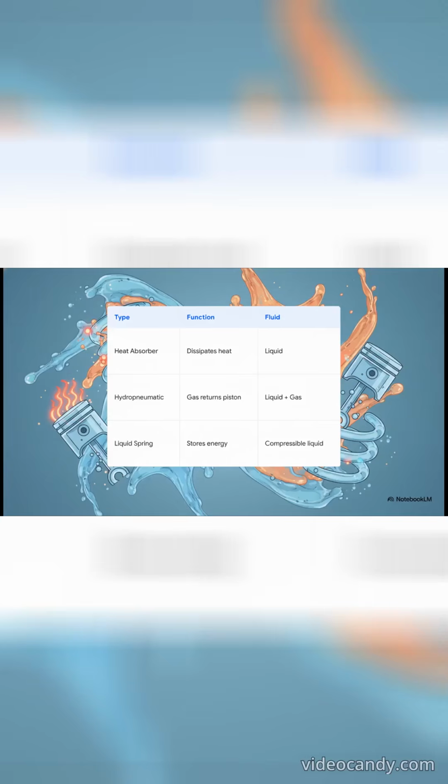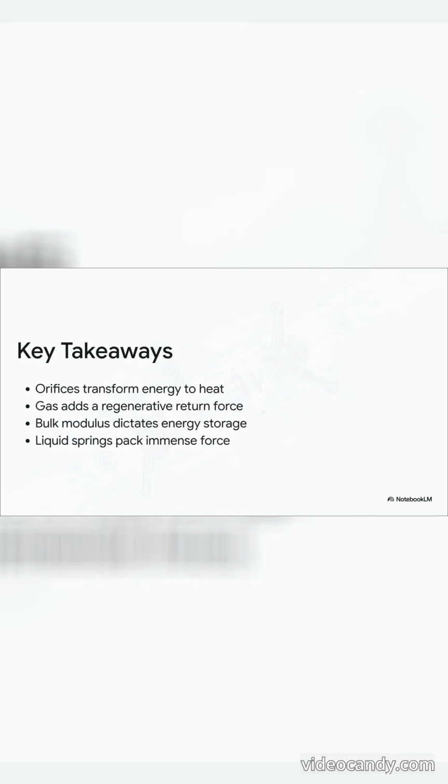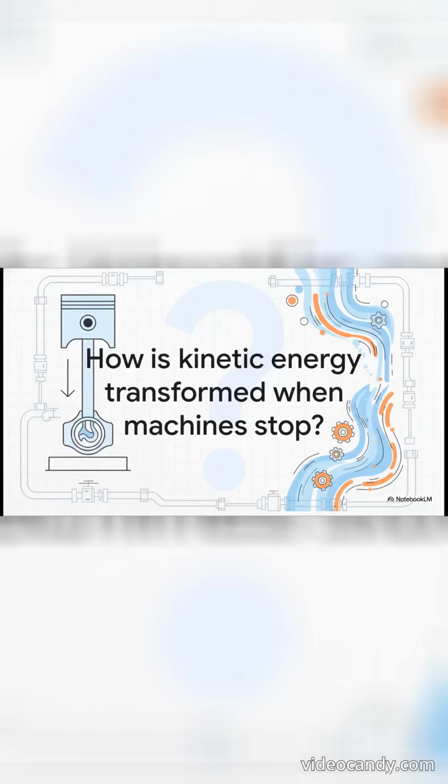All right, let's step back and summarize everything we just covered about fluid power and rapid deceleration. Heat absorbers just dissipate energy, whereas hydropneumatic and liquid springs actively use compressed fluids for return forces. Remember, orifices turn energy to heat, gas adds return force, and bulk modulus dictates the energy storage. Next time you see heavy machinery stop perfectly smoothly, ask yourself, how exactly is that kinetic energy transforming?